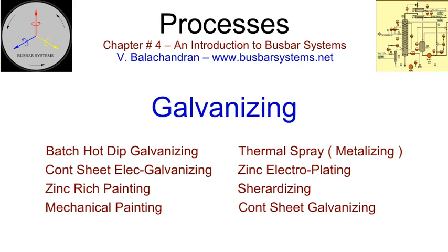Zinc itself forms a protective envelope called patina, which prevents a further attack on the surface. Zinc, in the presence of oxygen, water, and carbon dioxide, forms a compound which bonds well and is insoluble. Any damage on the surface of the patina is self-generating.